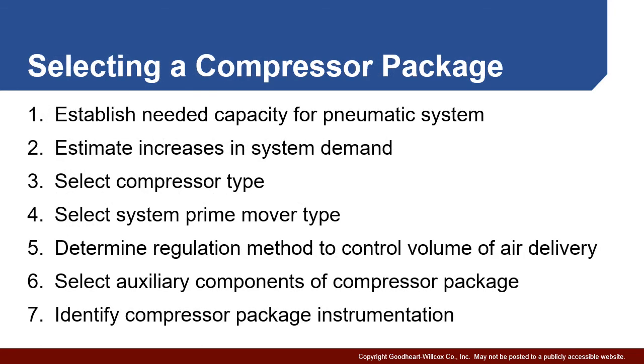Last thing I want to talk about is what's the process for actually selecting a compressor? Well, first thing you need to do is figure out how much airflow you need. So you're going to look at what your various tasks are, how that's going to be accomplished with the various cylinders, etc., and use that information to work backwards to develop what flow and pressure is going to be necessary.